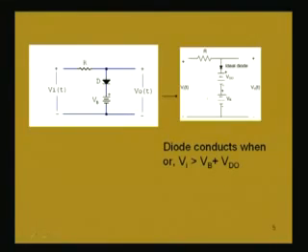The ideal diode is just to show the direction of the conduction current in the diode. So, the same circuit we are equivalently drawing again using this constant voltage drop model Vd naught. Others are the same, Vb is there, this source battery is there. The input voltage is sinusoidal, again we are assuming.